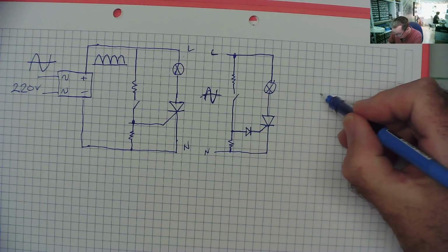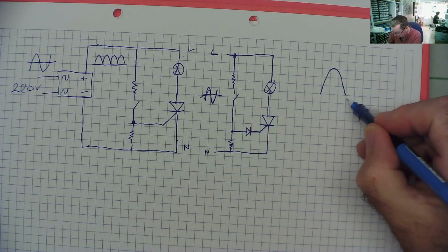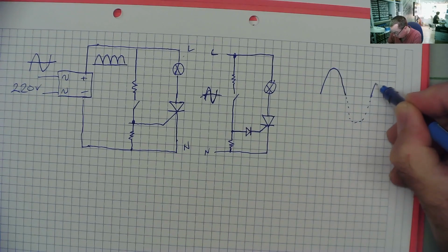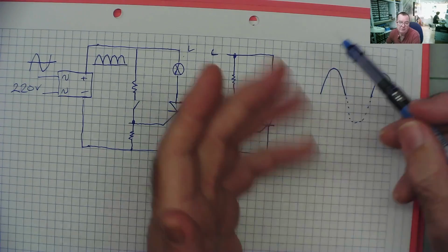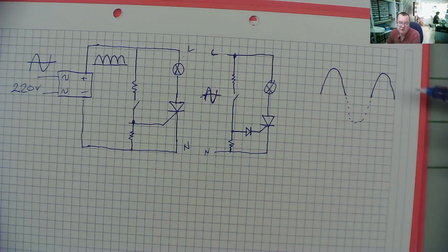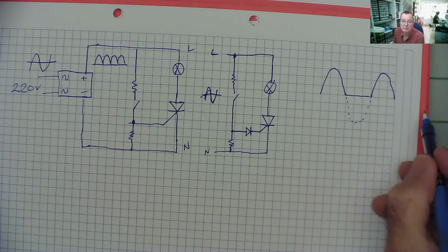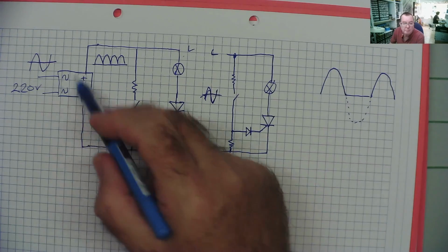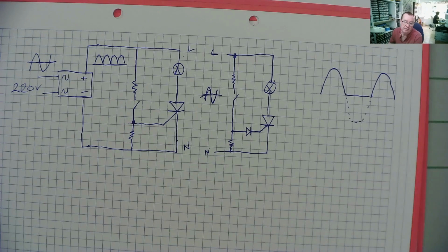You know now it conducts in the positive half cycle, and it doesn't conduct in the negative half cycle, okay? Conducts in the positive half cycle. So if we have a switch here, just a switch, and we close the switch, or a transistor and we turn it on, what you will get coming out is that. All the positive half cycles, okay? No bridge rectifier, so you won't get the full wave rectified, just half of them, half brightness lamp.